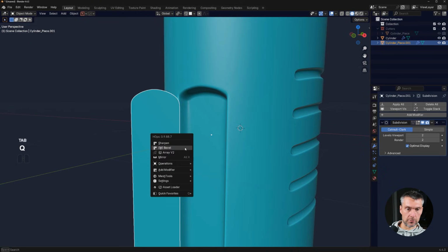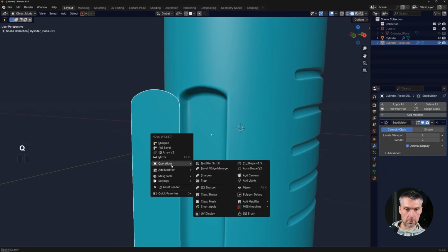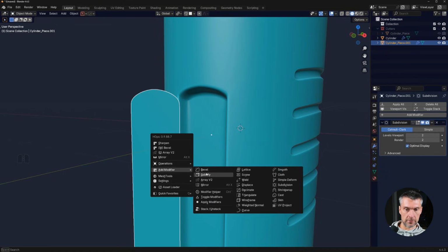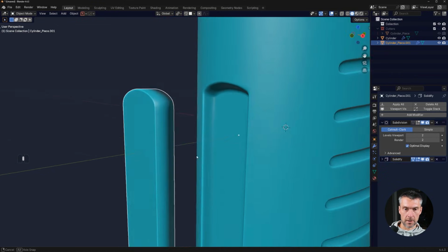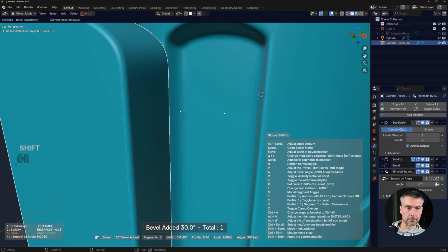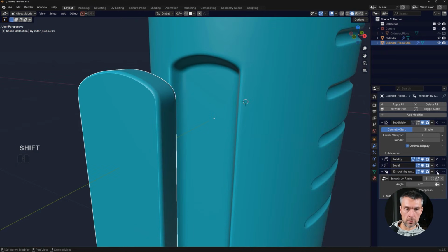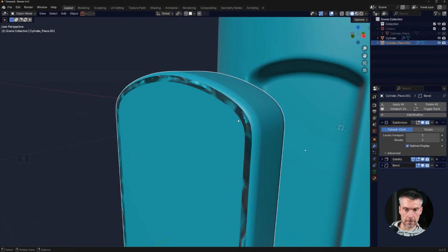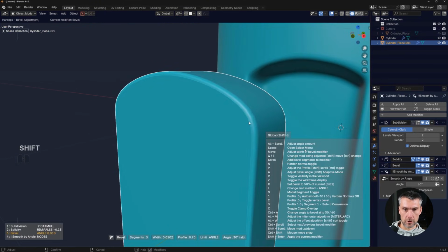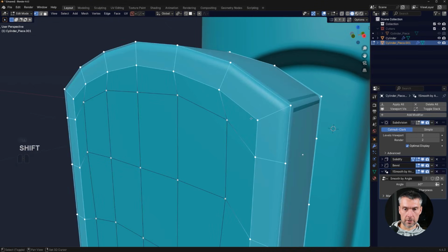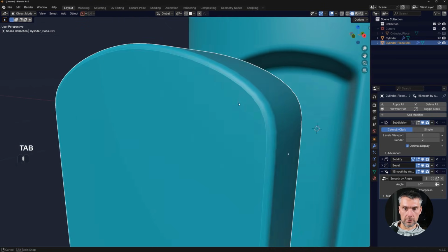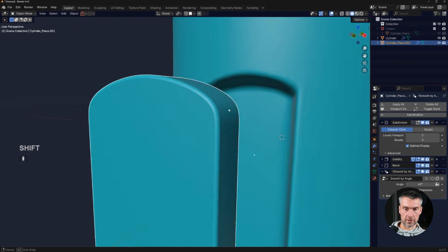So when I'm going to solidify this, right? So I'm going to go to operations and solidify it. So let's go here, right? And I'm going to run a bevel on it. Like a regular procedural bevel, just remove auto smooth because auto smooth will try to sharpen the edges. Just don't make it too large. You see the bevel is going to work because it's going to simply hold the entire structure.